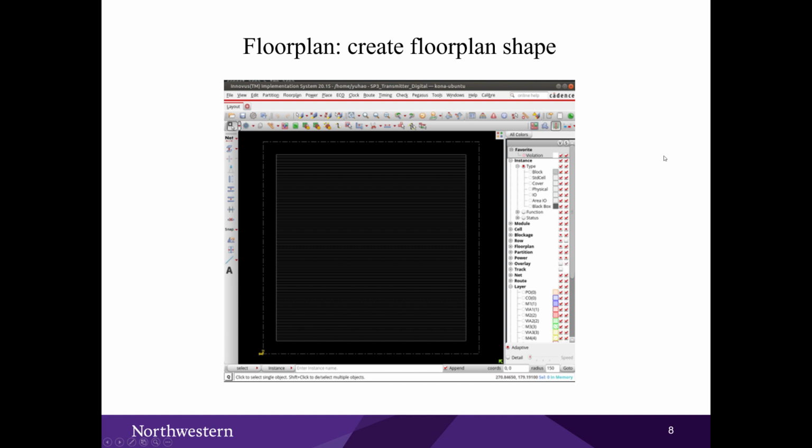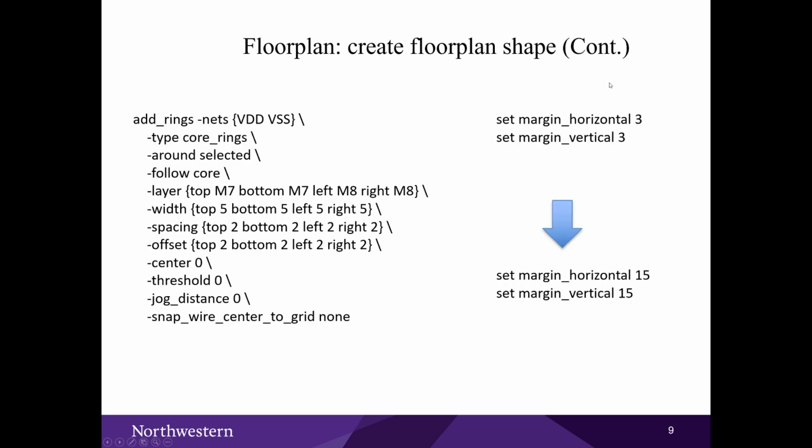So after synthesis, we need to do floor planning. The very first step of floor planning is to create floor plan shape. And in this step, we need to set 4 variables. The first is margin horizontal, and the second is margin vertical.